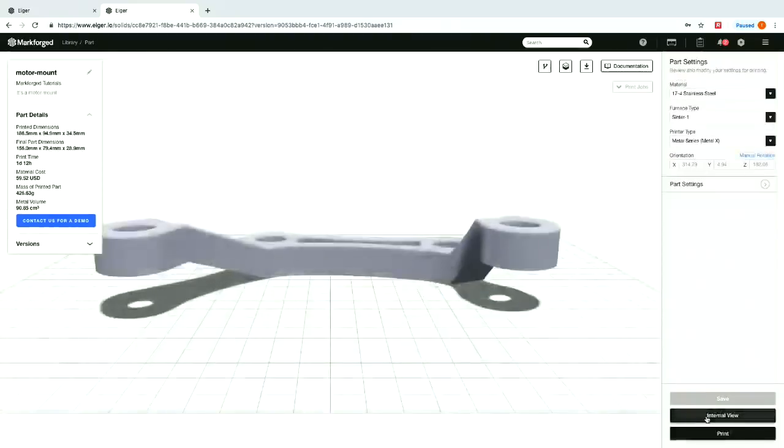So we got a couple of questions on H13. Can H13 be printed onto an H13 solid mother block, or does it shrink when sintered? I think it's asking if you can print our H13 onto another H13 block. So our process is an integrated process that is unique. When you print parts, they're printed on the print bed and then sintered in batches in the sintering furnace.